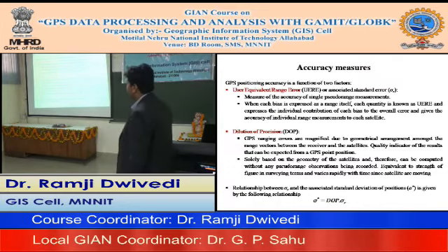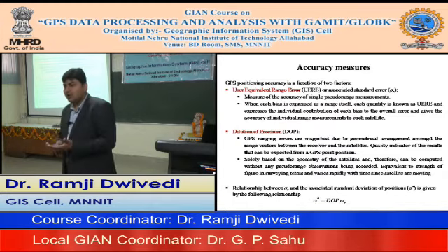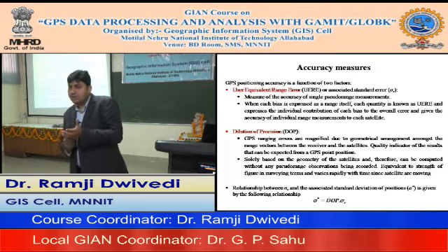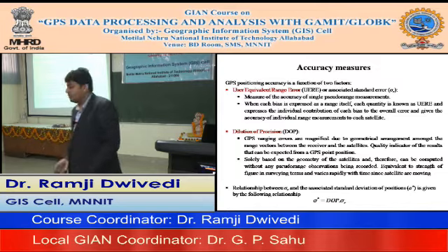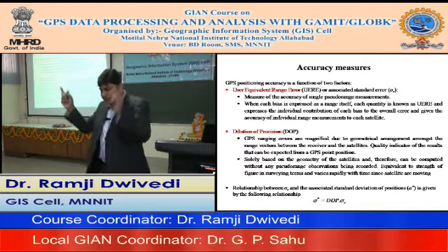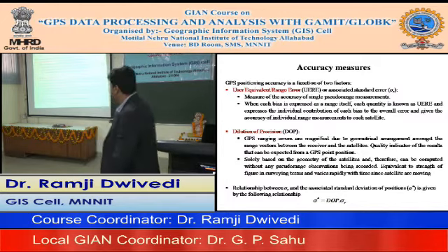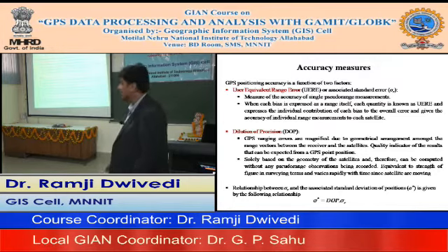And the other is the DOP. Whenever you turn on the receiver, you always have this DOP value coming in. How many of you have actually used GPS? Those who are using GPS see the DOP value coming up at the bottom, and generally we prefer a lower DOP value. Those values are related to the geometrical figure formed by the satellites and the receiver. We'll see what we mean by those figures and how we account for these DOP values.